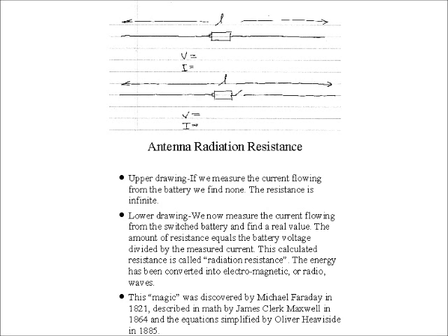If you take a voltmeter and measure across the antenna, you're going to get the voltage of the battery, no question about it. And if you put an ammeter in this circuit and try to measure how much current's flowing in that piece of wire, what are you going to get? Zero. Hank said zero. He's exactly right. With DC, you're going to get nothing. But watch this. See that? That's a switch.